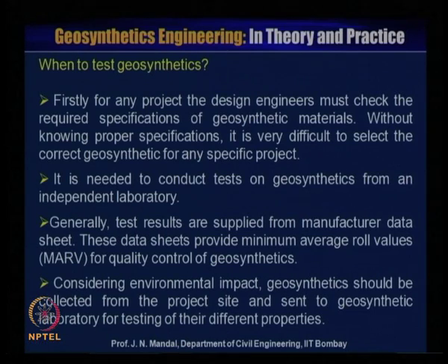When to test geosynthetics? Firstly, for any project, the design engineer must check the required specification of the geosynthetics material. Without knowing the proper specification, it is very difficult to select the correct geosynthetics for any specific project. It is needed to conduct tests on geosynthetics in an independent laboratory. Generally, test results are supplied from the manufacturer's data sheet.